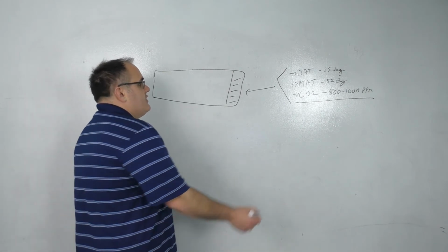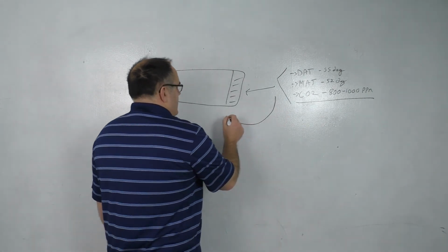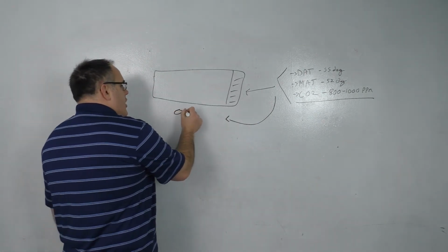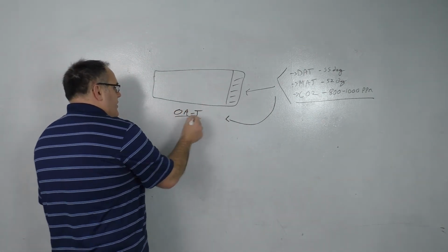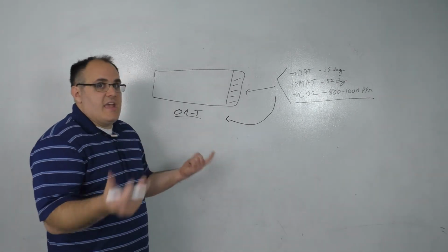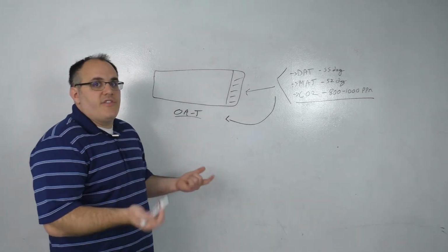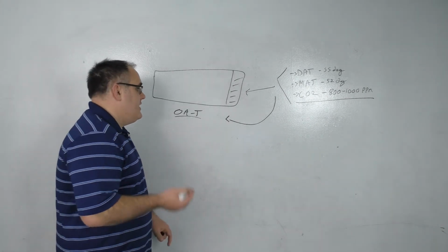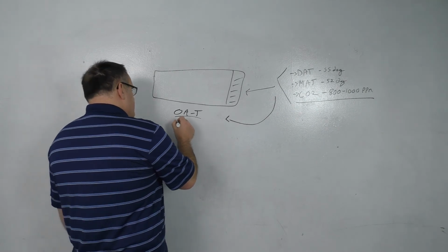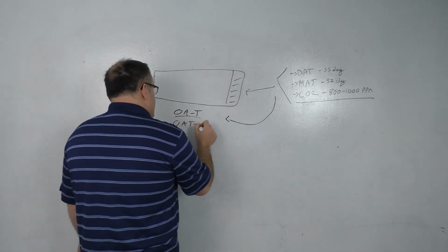Now, how do you go and enable economizer? That's another optimization strategy. So a lot of folks will just do OAT dry bulb. Dry bulb meaning it's not factoring in the moisture content of the air, it's just the air temperature. It's kind of what you see if you were to look at your phone and see air temperature. So you've got that right there. The other way is to compare OAT to RAT.